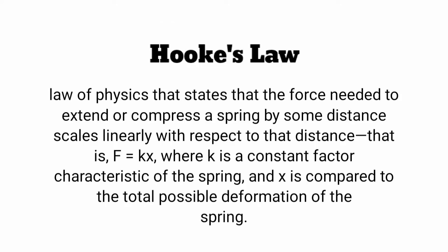The spring constant that we mentioned earlier is from Hooke's law, which is a law of physics that states that the force needed to extend or compress a spring by some distance scales linearly with respect to that distance. That is, F equals kx, where k is a constant factor characteristic of the spring and x is compared to the total possible deformation of the spring.